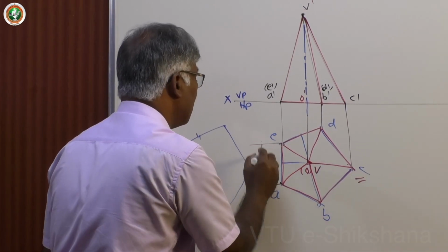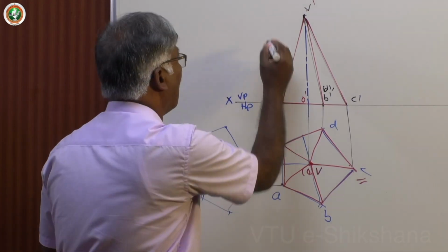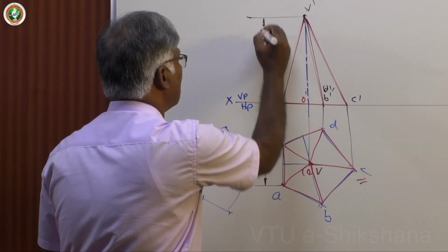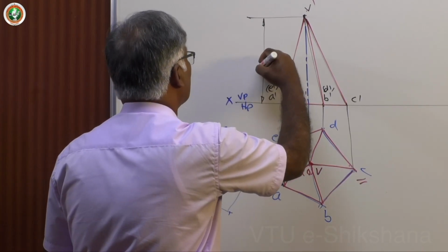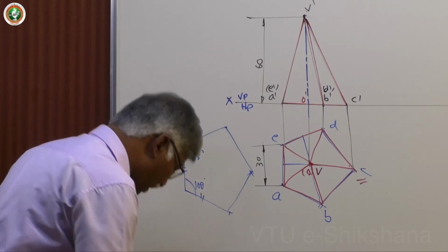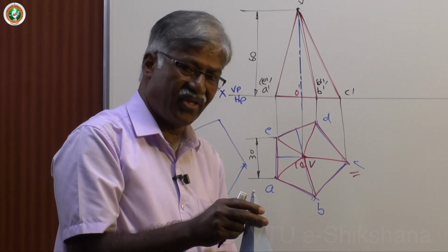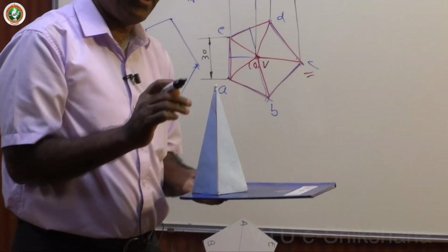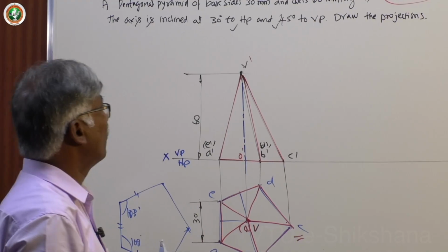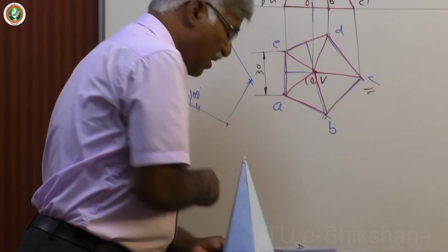So, whatever the dimensions given, you must keep it 30, and here with the specified thickness you have to keep 60. So, this becomes initial condition for the particular problem, first position. What about second position? Let me take this particular problem first. 30 degree to HP, inclination to HP only you consider and then do it.